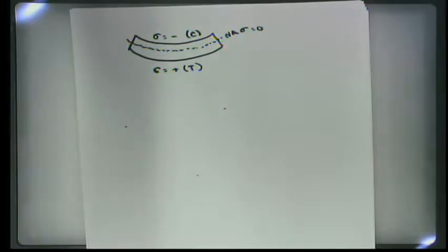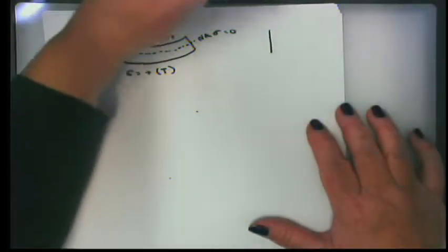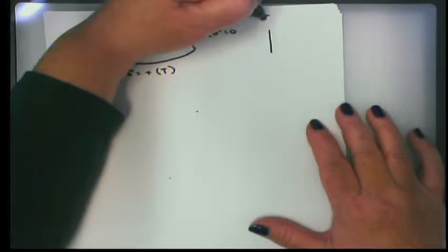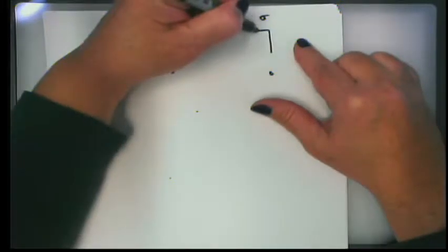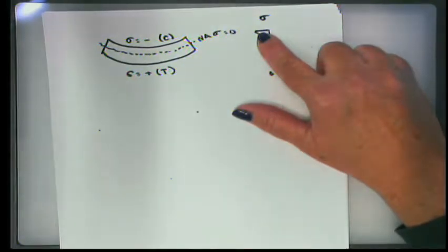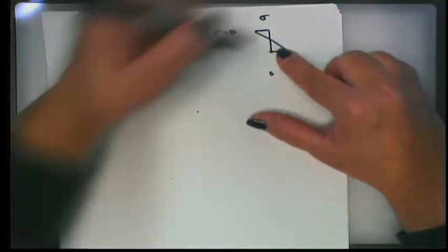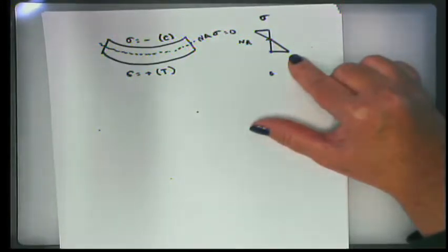Yes? Just a side question on that. Sure. The tension at the midpoint is going to be the same. Isn't it true that the length on it also? Yes. Oh, very, very true. When you look at that profile, we talked about this, but I probably didn't ever come out and say it specifically. If you look at sigma and you put an axis here, what we discussed is that sigma is a linear relationship where, in this configuration of bend, the maximum compression is at the top and then it proceeds linearly down to where at the neutral axis, sigma is equal to 0, and then it proceeds to a maximum tension right here.